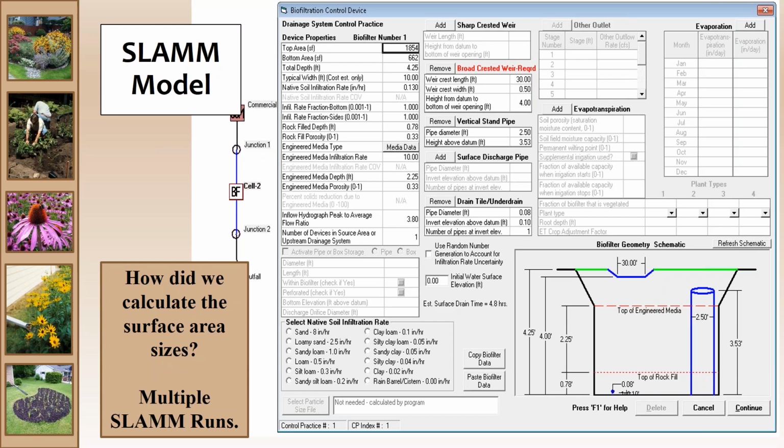So it keeps track of how much rain is falling on the rooftop, how big is the rain garden that you're building, what is the infiltration rate, and so in the end, you can make many runs with the model, as many of you know, to find out how big that effective infiltration area has to be, and how relative to how deep the pond is and so forth, to actually accomplish the goal that Perry was showing you in the table.